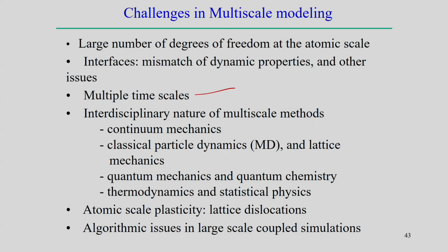But if we try to analyze the ultra short pulse laser welding process, the pulse duration may be of the order of femtoseconds or picoseconds. So we need to reduce the time scale in the analysis. Once we change the time scale, the analysis procedure can be different. For this ultra short pulse laser welding process, we cannot simply apply the heat conduction equation, Fourier's law of heat conduction. So we have to analyze at a different scale.